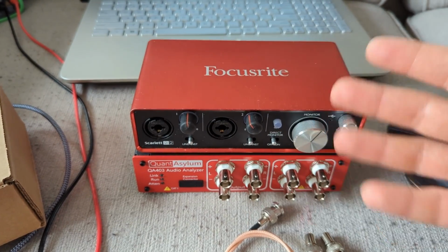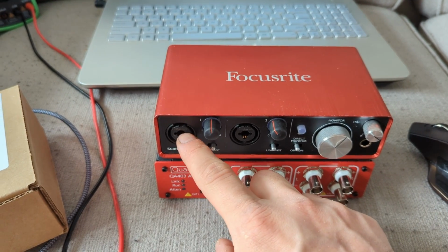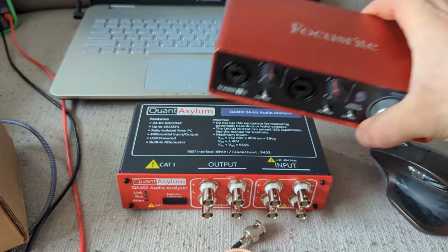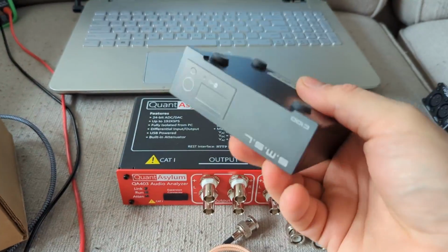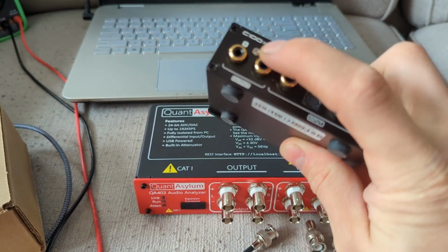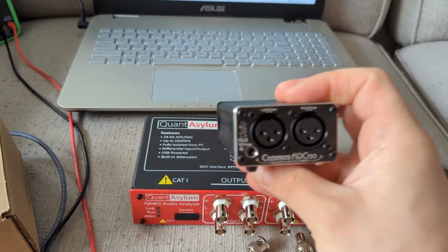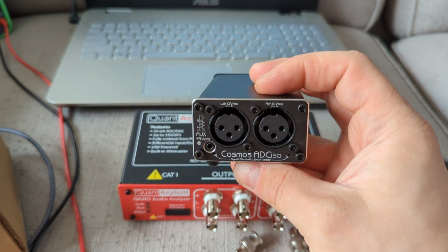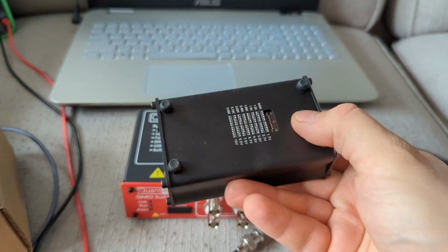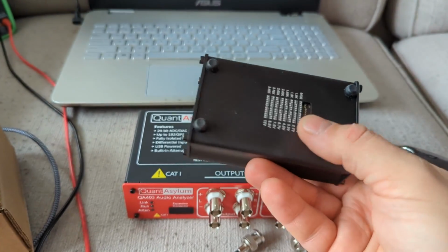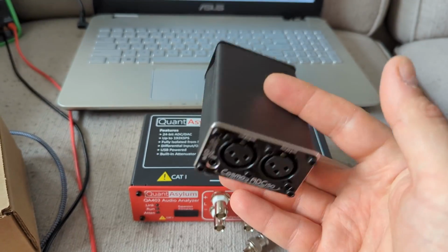In order to go around all of this, I have to increase the gains on the amplifier, and I need a kind of voltage divider to lower the voltage that's going into this thing. Now, very recently, if you saw my previous video, I bought something else. I bought an SMSL DAC that can output 2 volts, twice as much voltage compared to the Scarlett, and I bought an ADC, which is a Cosmos, and this Cosmos can take either 10 volts here, or 43 volts here, so it's much better, and this combination is much cleaner. It's going down to like 117 dB.